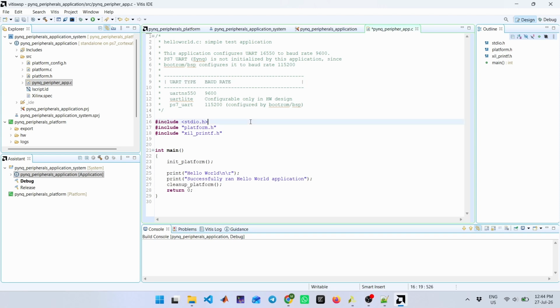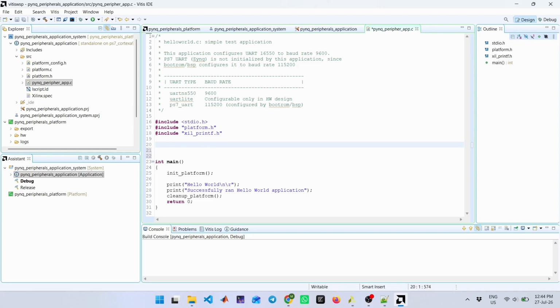We need this one for connecting to the board. So now you have to write a C application inside Vitis. By generating and compiling the platform, it's giving us a file that I have to include in our C file. That's called xparameters.h, and this xparameters.h is containing the data regarding the registers that are used in our custom IP.